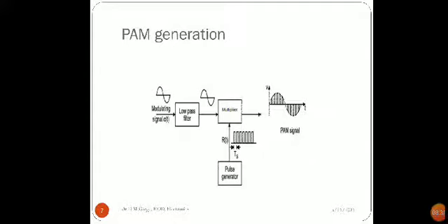Now this information signal, which is band limited, is multiplied by the pulses. So there is a pulse generator which is generating pulses of time period Ts. It means its frequency is the sampling frequency Fs. After multiplication of these two, you will have the output which is shown in the diagram. Of course, we have shown output with dual polarity and natural top. You can have different multipliers or some modifications in the multiplier circuit, where you could have the single polarity signal or flat top PAM output.